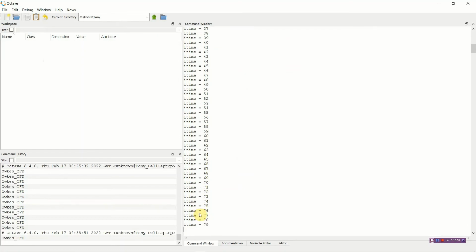I hope it's clear that what's going on here is that we have some imposed velocities at the top, and these discretized finite difference equations are spreading these velocities through the mesh. At each time it's solving continuity and momentum equations via this Poisson's pressure equation, and coming up with hopefully a new set of velocities and pressure distribution for the complete cavity. I'm going to just stop the video for a moment while it's running, and I'll come back to it just before it's finishing.